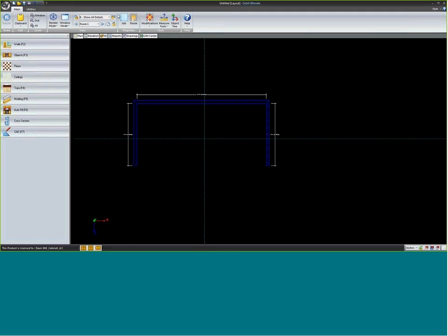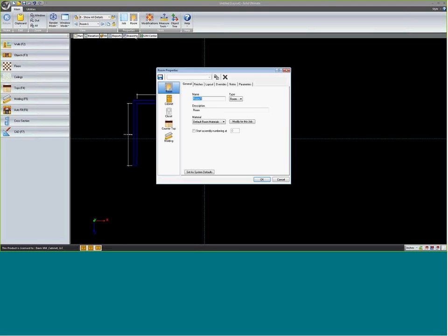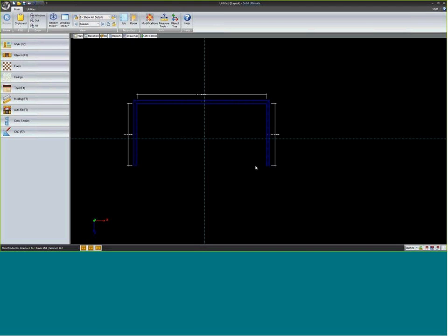So when I set up a room, I like to go to the room button first and change my layout tab to whatever I want, particularly the height and the soffit height. The thickness you can adjust if you want to, but usually I adjust these two. And you can also set it as your system default if you want it to always bring up that size.